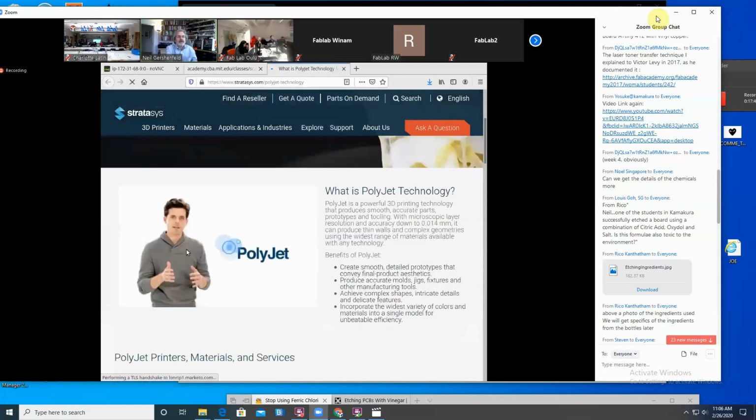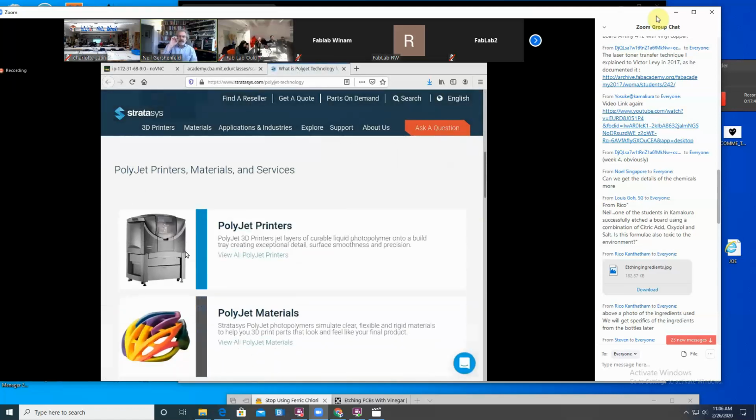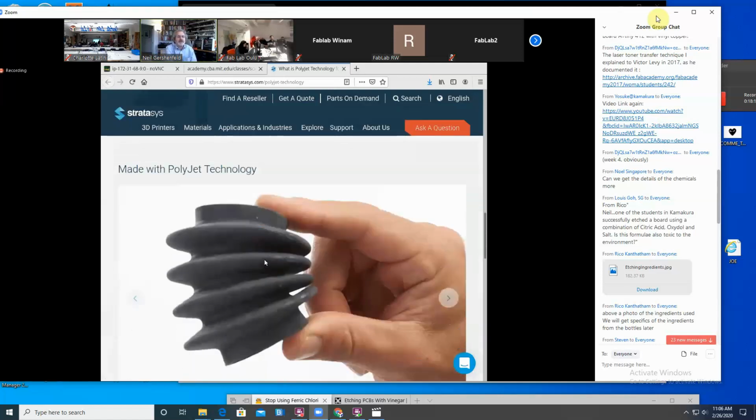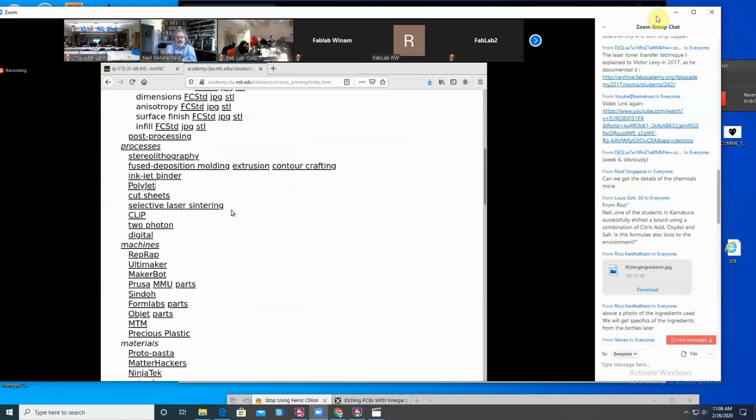Polyjet, which came from Objet, now merged with Stratasys. Its inkjet prints the same kind of resin used in STL or similar, but it does it with a print head and little droplets and fuses those droplets as it goes. So these are much more expensive machines. These machines can cost hundreds of thousands of dollars. But this is a nice process to print functional prints that have many different kinds of materials. So you can vary over it the material properties, you can vary the color. And so that's been the nicest process for multi-material printing.